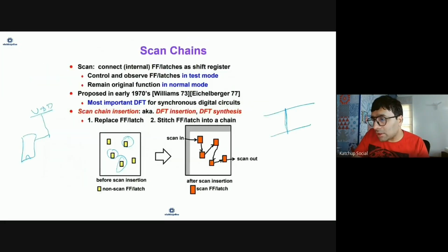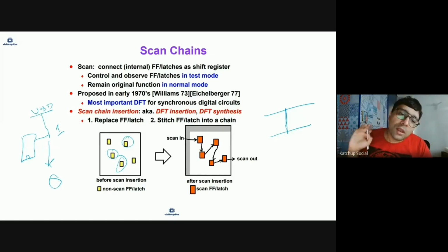Now this signal will always be 1. You can never have a 0 value on this because it is directly connected to high voltage. Since it cannot have a value 0, that will cause the design to fail. But how do you test that it cannot have a value 0?